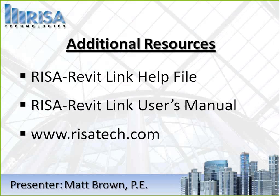I'd just like to mention that if you are submitting a Revit model to us that you're having a problem with, I run into this all the time, please relinquish all of your work sets and, if possible, send me the central model, because otherwise, of course, I run into all sorts of permissions issues when I go in and try to figure out what you need to do to fix your model. But if you get in and play around with the link, it's all very self-explanatory, and you should be able to get the hang of it pretty quickly.